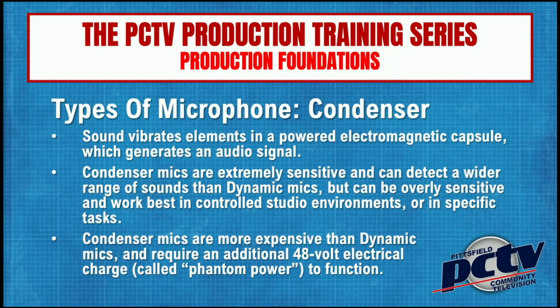And because it's electromechanical, it doesn't function without being powered. Some microphones that are powered in this way will have a battery that you can plug into the body of the microphone. Many of these microphones will also accept an additional 48-volt electrical charge, which we call phantom power, to function.